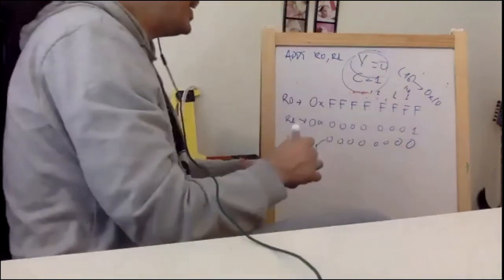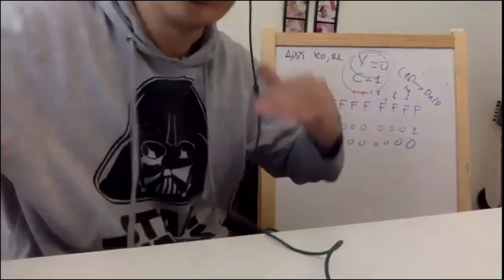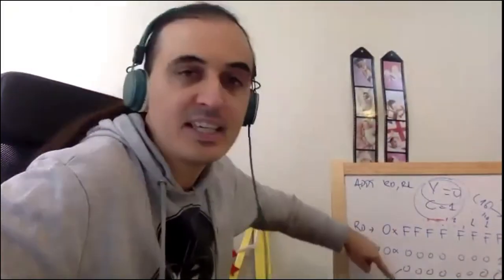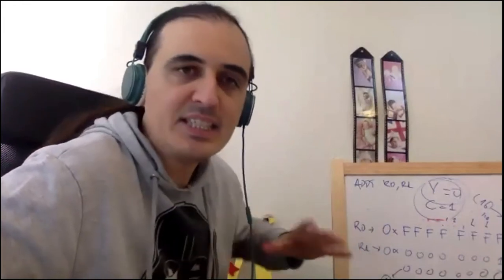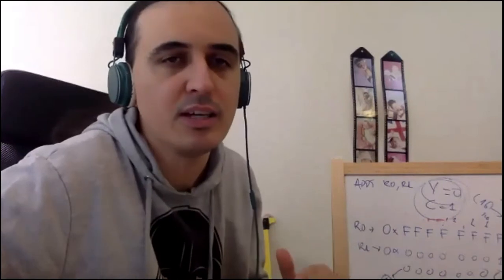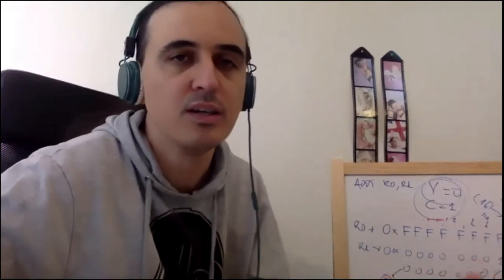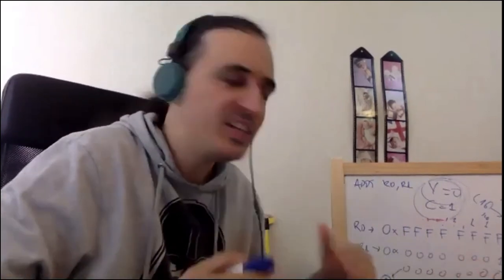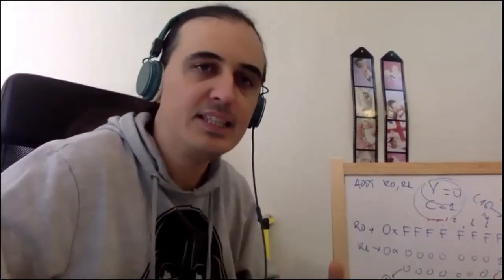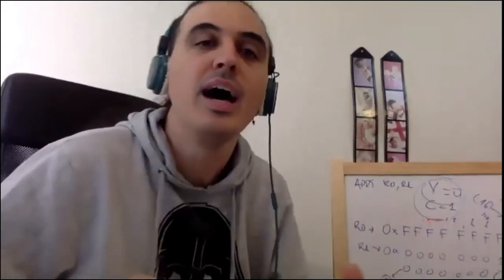Good. The arithmetic logic unit has an adder, guys. The adder did a summation, and in the end there was a carry. So this, I'm calling it a carry. There was something residual. I'm not going to call it carry because I don't know yet if it's a carry or overflow. So if there's a residual digit here, I know that either the C or V bit will be set. I don't know which one. How am I going to decide? I'm going to teach you now.